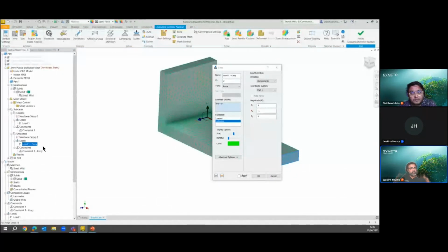What I'm trying to say here is that when you put a load on this cantilever, the second subcase will start from the first subcase when it finishes. And then what you're looking for is the deformation of this component as a result of that load, and also the strain value, which we're trying to establish, so that we can exclude these high stresses.